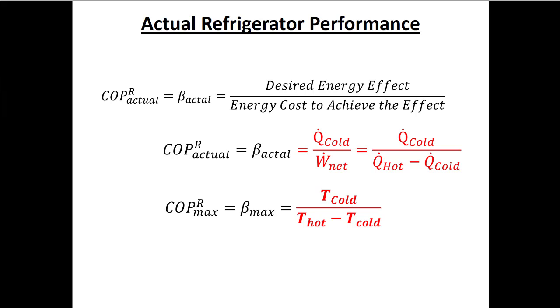And then if I'm talking about an ideal system, then I can go to the Carnot coefficient of performance, which is T over T minus T. So T cold, because the energy benefit happens on the cold side, divided by T hot minus T cold. So again, this Carnot thing is not actually possible, but it's the limit of what's possible. So it gives us something to shoot for. It lets us know where the line is. And we'll talk about later that just the form of this kind of idealized simplistic model gives us some hints about what we can do to improve efficiency.